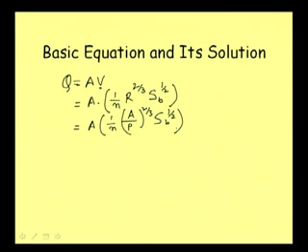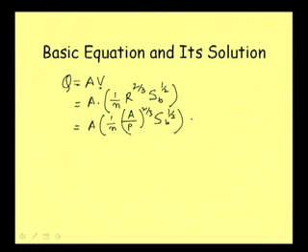Well, now for a different section, this area and perimeter will be different. Let me take one section, say a trapezoidal section. Let me consider that this is a trapezoidal section, and say my flow depth is this much. This depth, let it be y. And if it is uniform flow, we can write it as, of course, y n, that is normal depth. Well, for the time being, let it be y. And then for this section, say this is my bed width b.